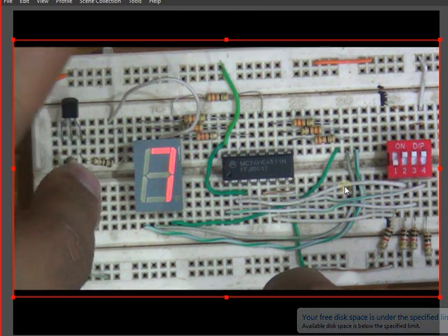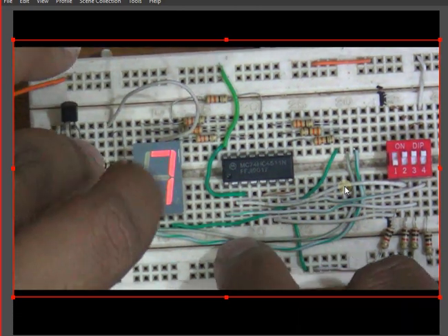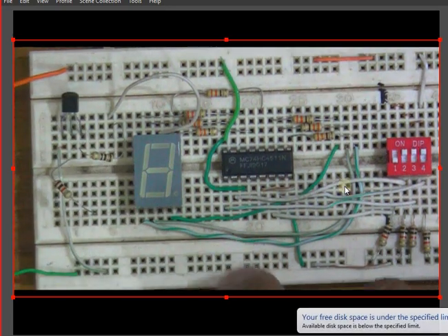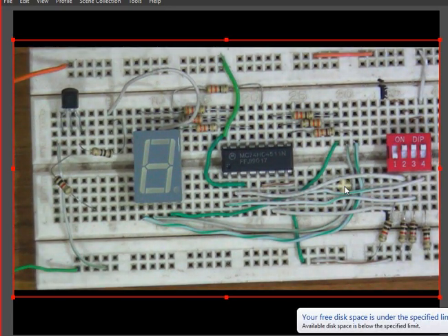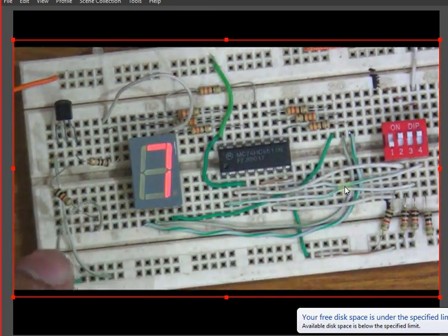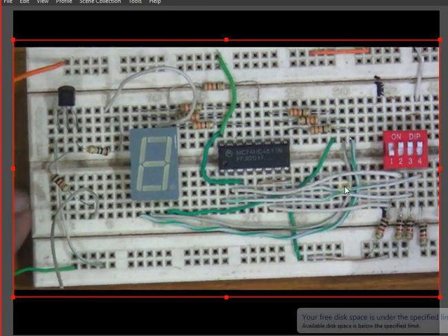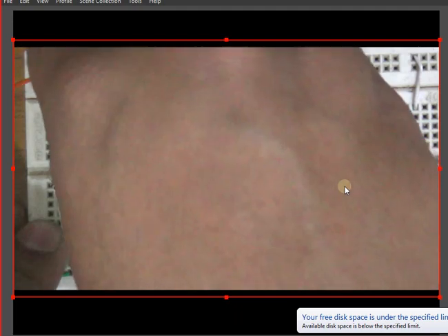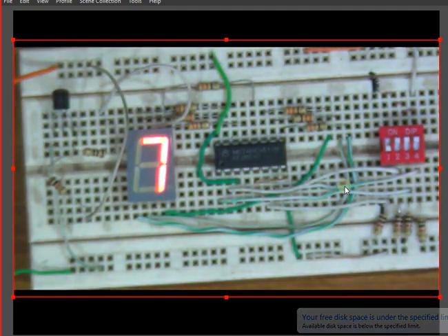So I'm just providing that milliamperes current, but I want to provide it through a 5 volt signal particularly for this purpose. So what I will do, I will take a jumper wire and I will connect. So this is my jumper wire connected over here. Even if I now connect the other end, you can see now it is turning on. Let me just straight it on. And here, if I connect it to the 5 volt signal, now this is turned on.